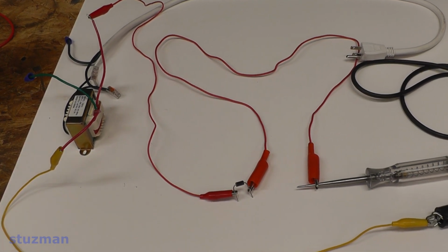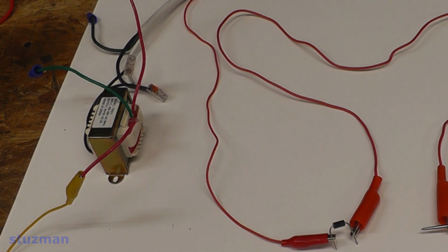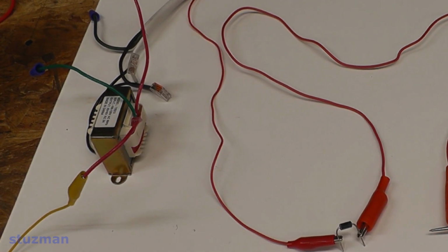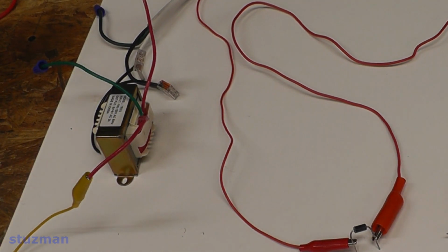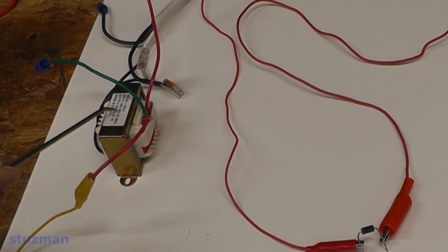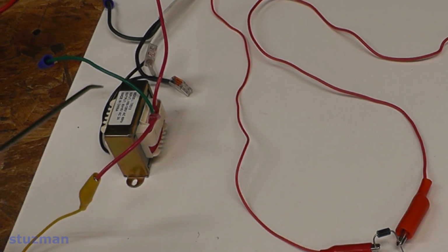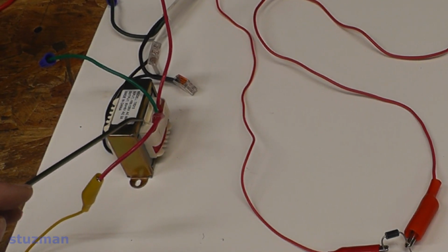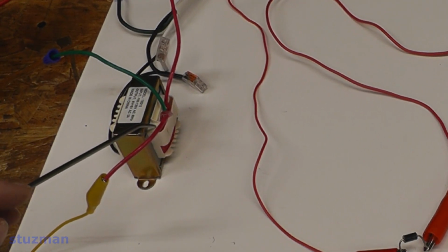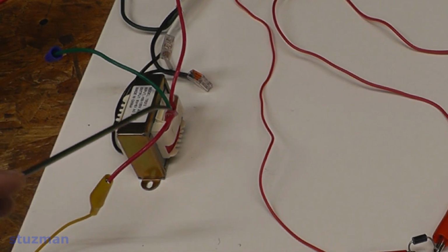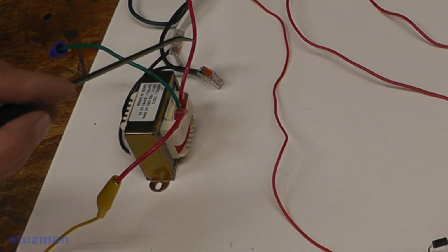Alright, let's take a look at this half-wave rectifier, and this time instead of using a DC power supply, we're going to be using an AC that's going to be feeding the diode. What I have here is a center tap transformer. On the primary, it's going to be feeding 120 volts, and on the secondary we have a 12 volt center tap transformer. I'm using the 2 outside legs, so that's going to give me 12 volts AC RMS.